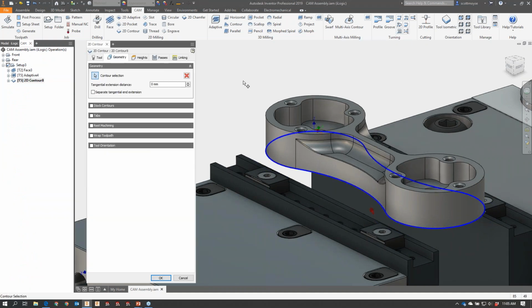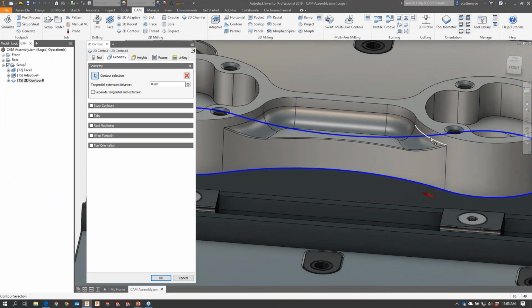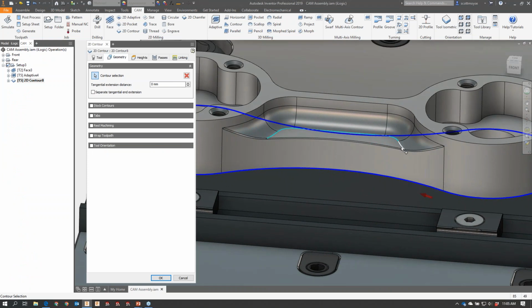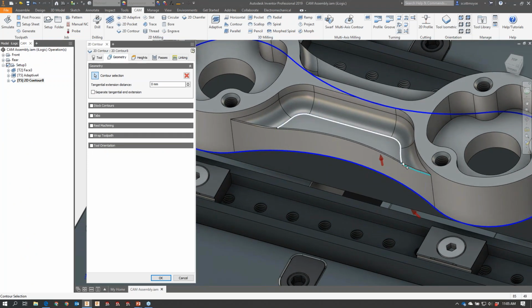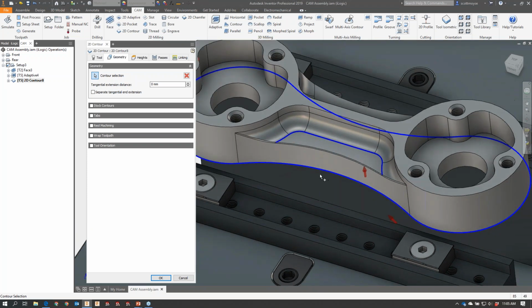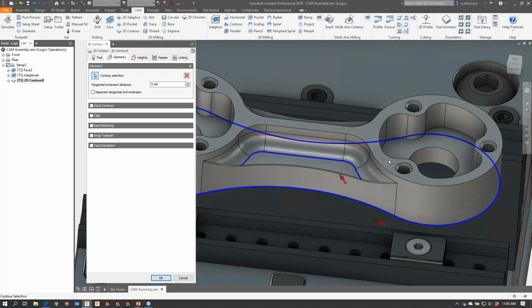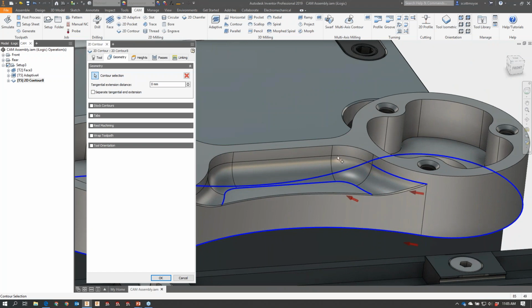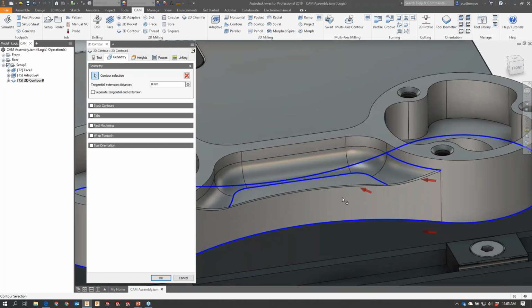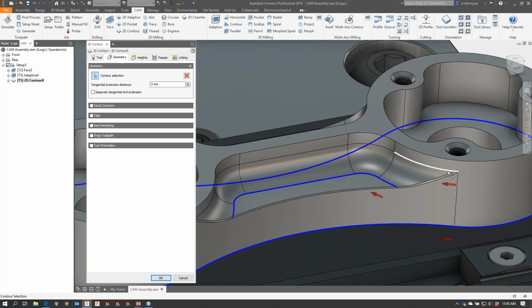All right. So now we want to add some additional contours. Now, when I pick this geometry, we can see now we've got an open contour instead of a closed one. And in some cases, when you select open geometry, it doesn't automatically find all of the edges. This is where you need to select the blue line a second time, and you'll see this little mini toolbar appear with these filters for closed contour and open contour.